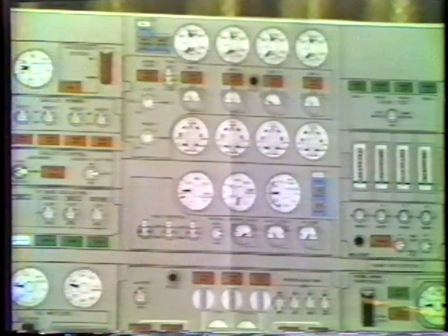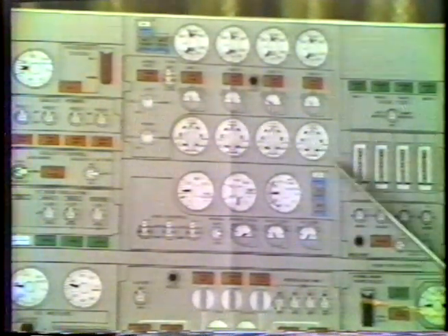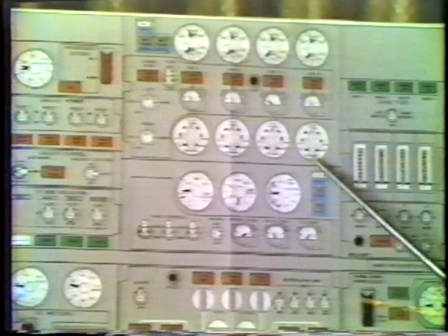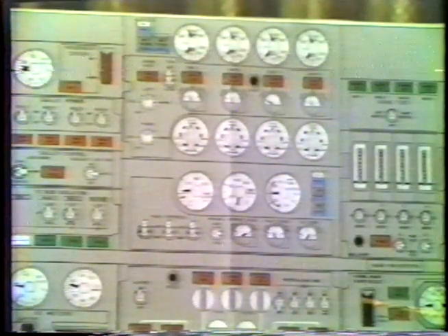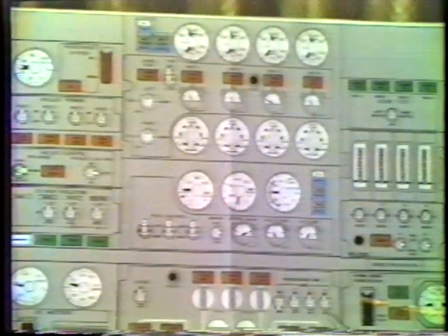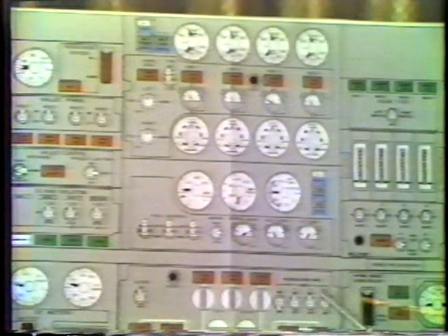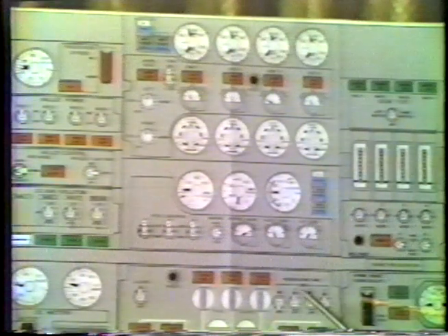One very important thing I would like to point out: if all 4 auto controllers are in the manual control range, no matter where the trim air valves are, the packs do not have a signal to control the temperature, and they go to the full cold mode.